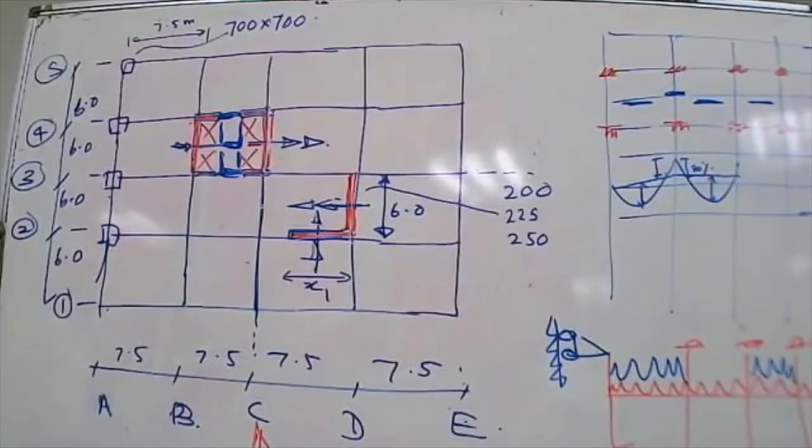Sometimes I want to know whether it is necessary to go for a higher stiffness beam than the column always, because sometimes we have to select the dimensions of the beam compared to the column. Actually, what you have to make sure is the column is larger than the beam, not vice versa.